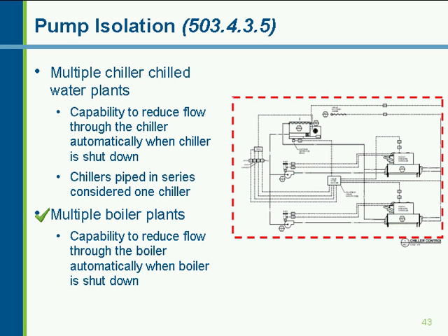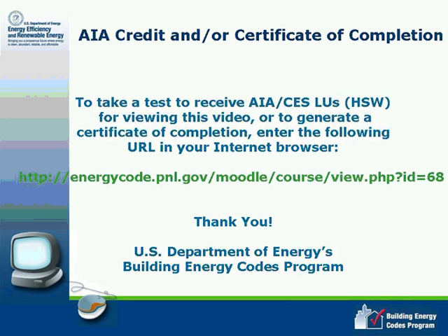Okay, there was a question about the types of exceptions I mentioned for energy recovery ventilation systems per the IMC. Can you state some of those again? I just gave 2 examples, and I don't have the IMC with me, so whoever wants to verify this should probably check. But I believe that the IMC has a prohibition against doing heat recovery from systems that are exhausting toxic fumes and from kitchen grease hoods as well. But that should probably be verified, but I believe that's correct.